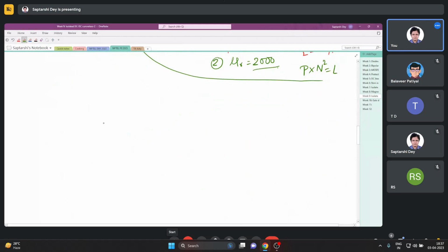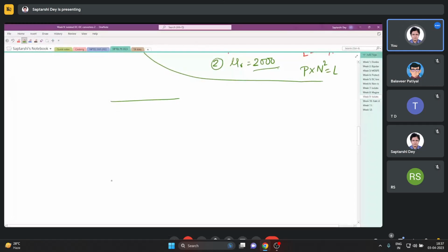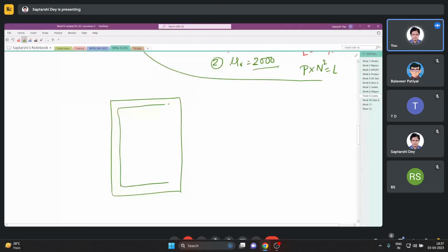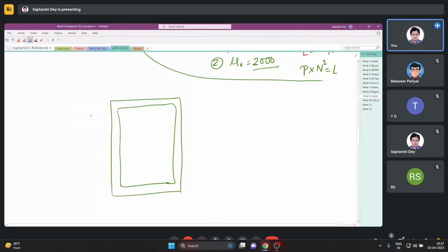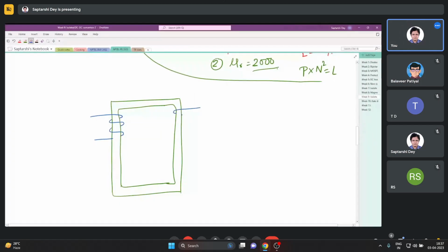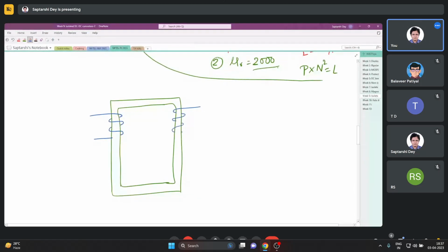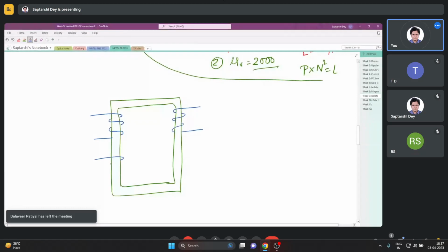I discussed during the flyback converter also, that if you are confused about the polarity of the voltages and currents in case of DC-DC converters, simply draw the magnetics and the windings with proper sense, so that you can put the dot conventions on them, then draw the rest of the circuit, so that you can figure out the voltage and current polarities.